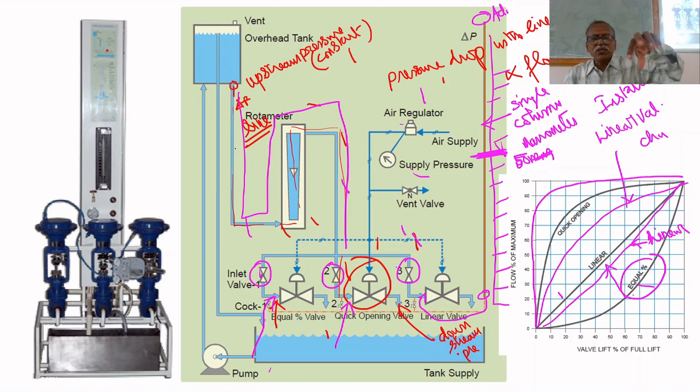Whatever the flow rate, you can bring the level back to the same level as for maximum flow rate. If the flow rate is decreased, the level will go up, and by adjusting the hand valve you can bring it back to 50 mm.